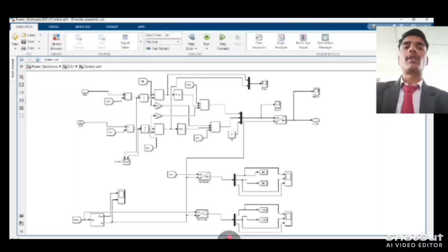First, for the reference and feedback path, the upper section has blocks labeled as reference input, VREF and QREF, where VREF is the active voltage reference, and Q is the reactive power taken as a reference. Then the feedback has voltage output and current output. These signals are compared using a subtraction block to get an error signal. This error represents the difference between desired and actual performance.